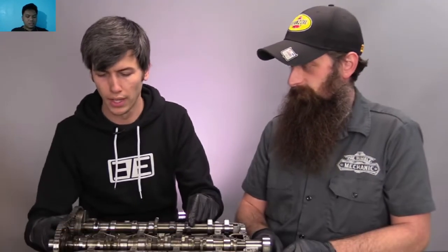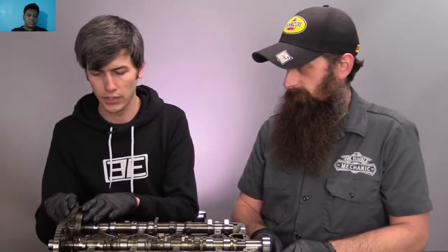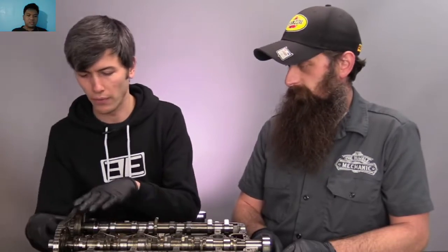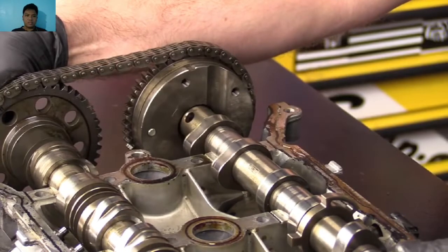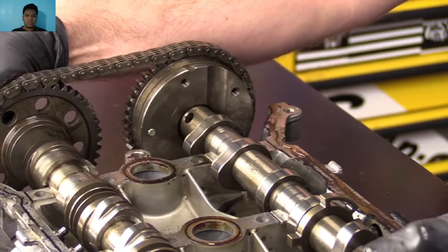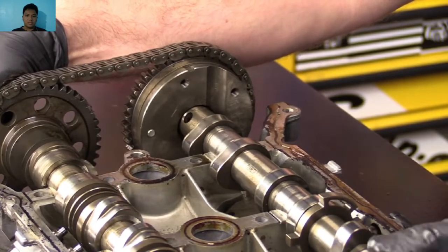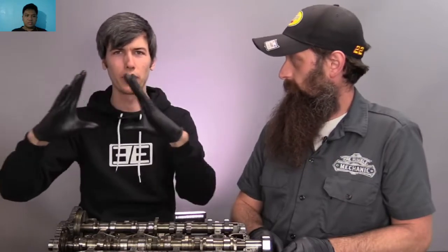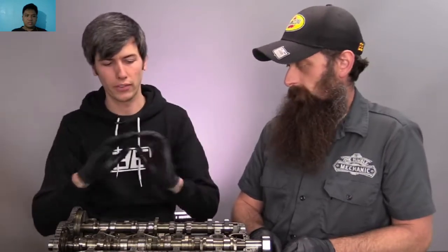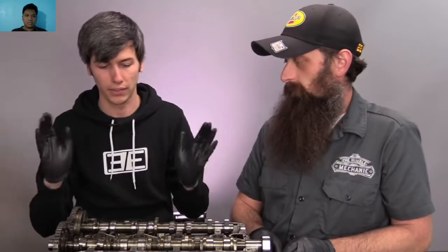So moving along to the intake side, as you can see, just a single cam profile, and what we have here is our variable valve timing. If I hold this stationary, you can see the chain won't move, and we can advance it or pull timing back and retard the timing. On the intake there is only one cam profile, so all we're doing is, let's say you have your cam profile open, close, you're just shifting when it opens and closes back and forth, and that's all you're doing. The cam profile remains exactly the same.